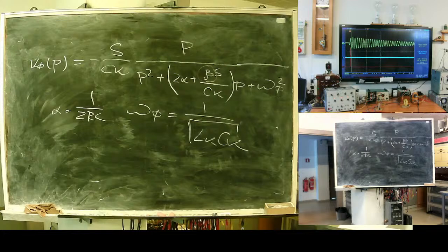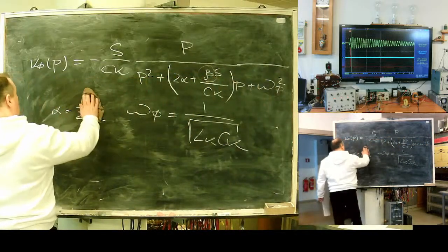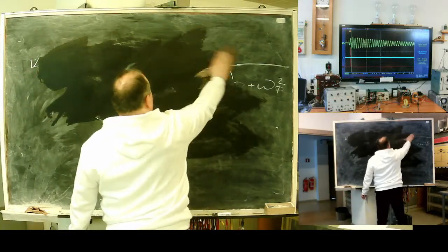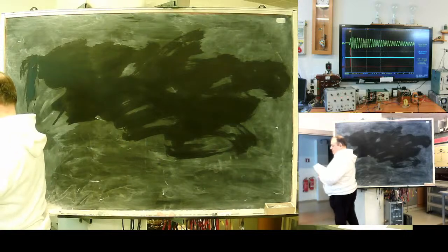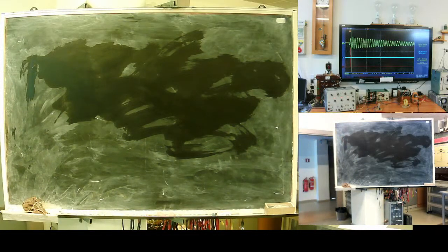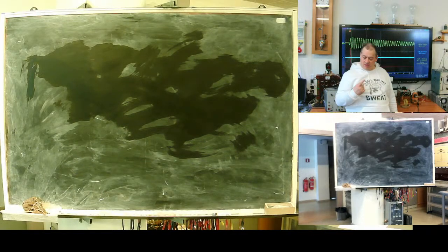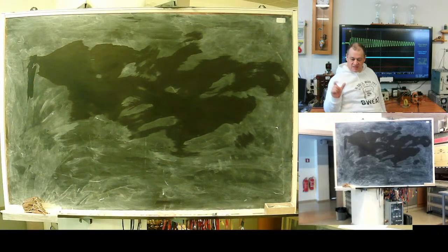I need a system with a known open loop equation. Okay, one point here: my linear part is inverting. A single triode amplifier is inverting; it has a transfer factor with a minus sign.